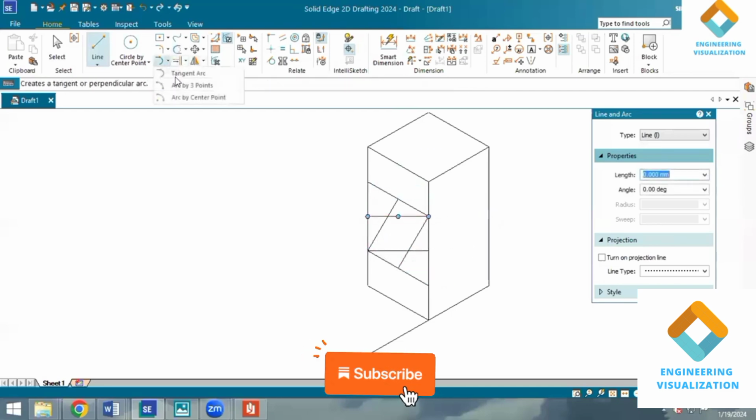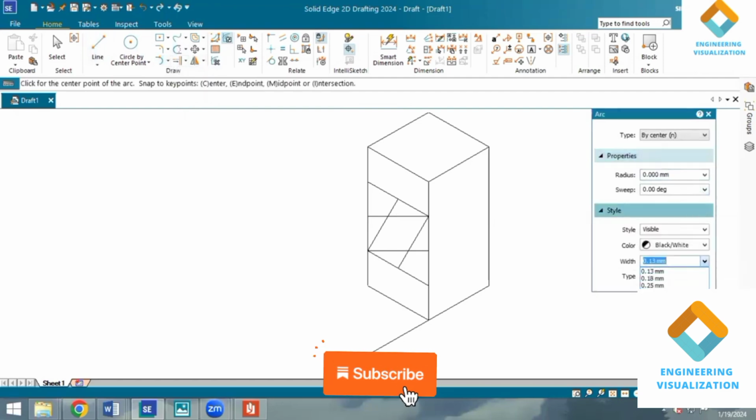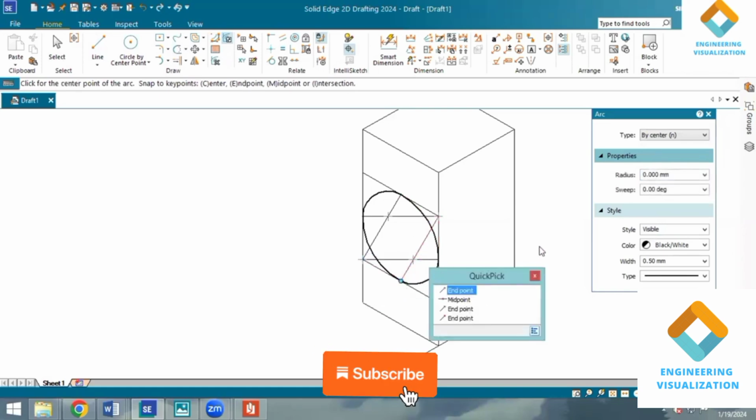So now using the arc by center method. So here we will be constructing an arc to construct the ellipse, taking this length, draw an arc. Same way from here to here, take this length, draw an arc. Now for the third point, take this as a reference point, taking this line, draw an arc. And same way here also, take this length and draw an arc. So we have completed an ellipse here.